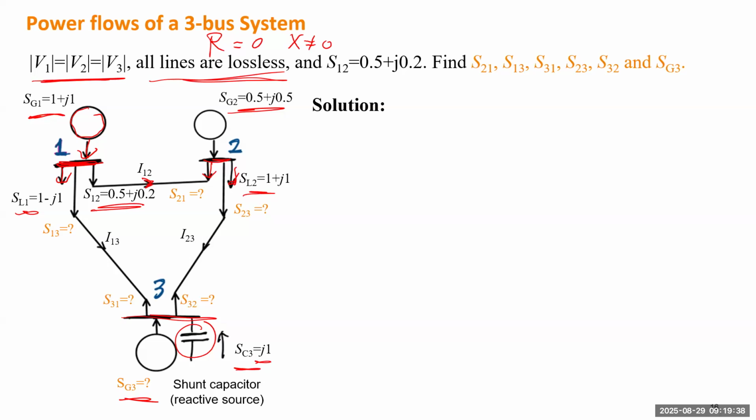So even for the line connecting bus 1 to 2, we want to calculate the complex power leaving bus 2. You may wonder, because this is just a single line, is the complex power that comes from bus 1 the same as the complex power at bus 2? Maybe not, because the transmission line itself is equipment, so you also have some reactance. So we need to utilize the complex power balance principle to finish the calculation.